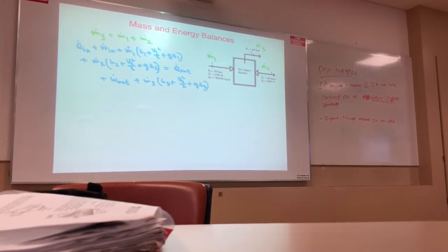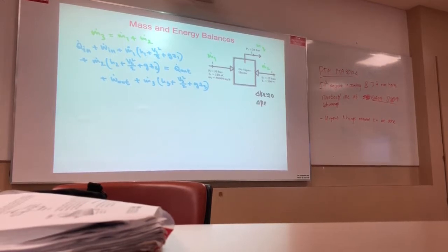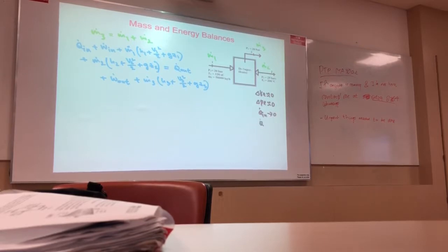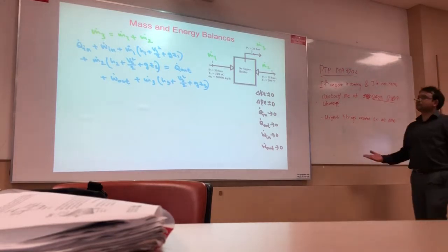In that question, we assume there is no change in kinetic energy, as given. There is no change in potential energy, so that is 0, right? And is there any Q input externally? No. There is no heat output. There is no work interaction, since this is a small chamber, it doesn't produce any. What if it is a big chamber?